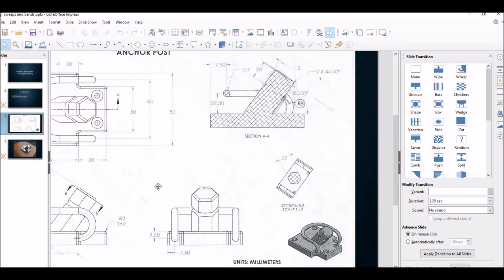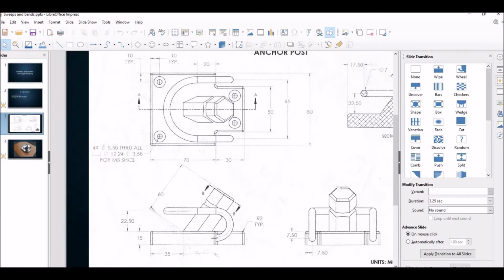Now normally what I should be doing is modeling in place. It's so much easier to model in place. For example, I should have modeled this hex post in place, but I wanted to model it outside of the component so you can see what it looks like and see how I'm doing things without any interference. But in all reality, the best practice is to model things in place. Anyways, I'm not going to worry about it right now.